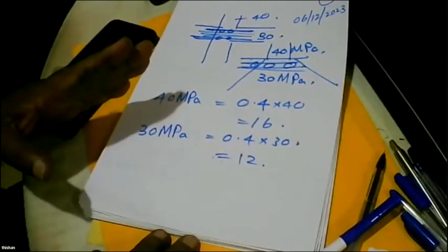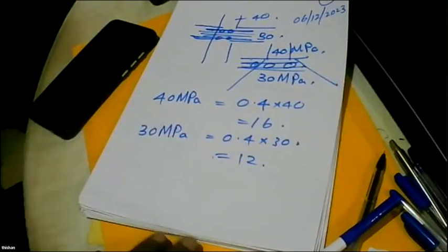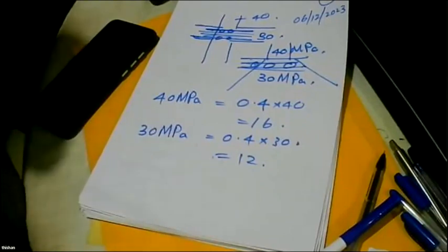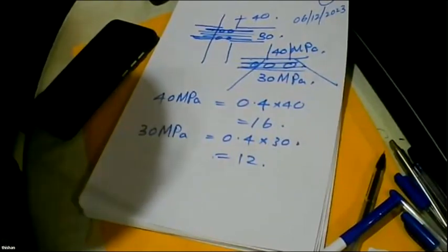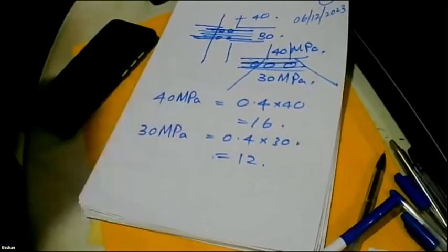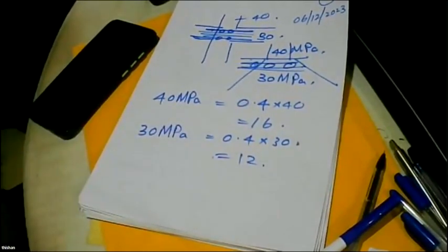But if you are going beyond 25%, you have to be careful. You have to do tests. At one point in Sri Lanka, I think for the ICT tower, ICC did it. Engineer Samitha Jayakodi did most of the concrete technology part. I think they went up to about 35% or 40% fly ash. But it has to be done very carefully, purely for the temperature control.